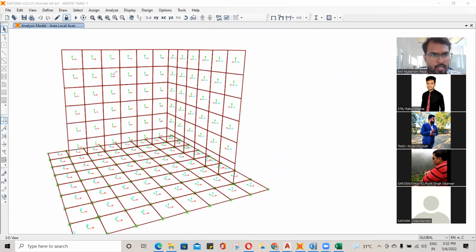If I want to calculate the reinforcement for wall 1, I have to check the moment M11, and from that moment I will calculate the Ast, and I will provide the Ast for this direction, correct? Because our red is along this line, whatever I am drawing. I'll change the line color to blue, otherwise you'll get confused.